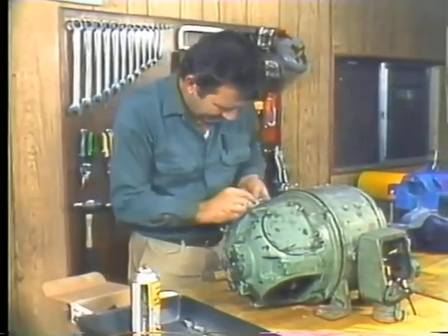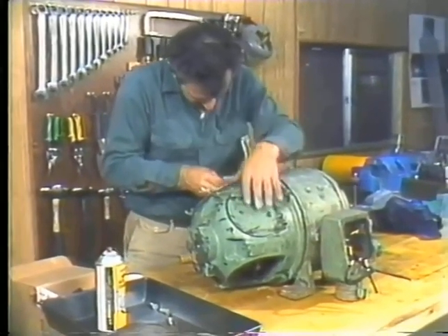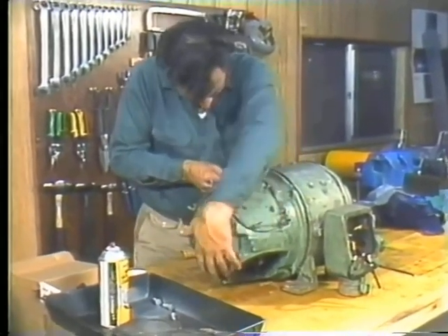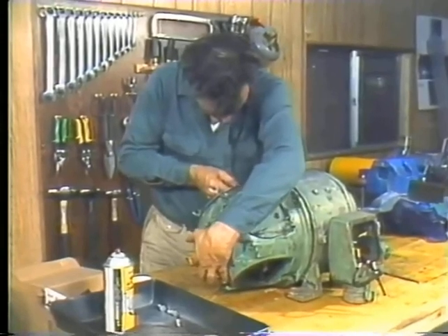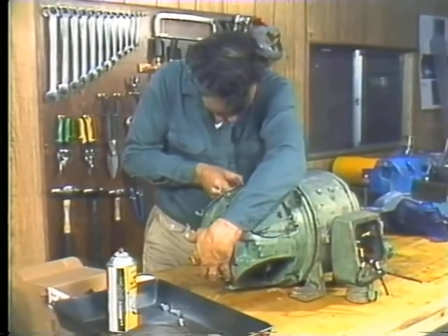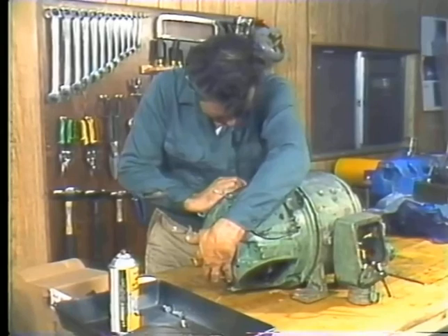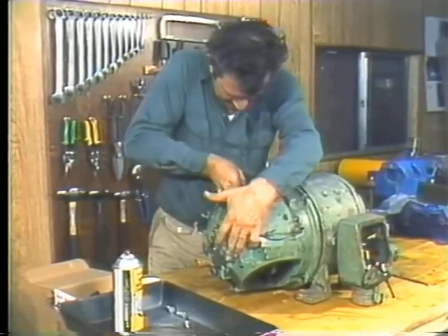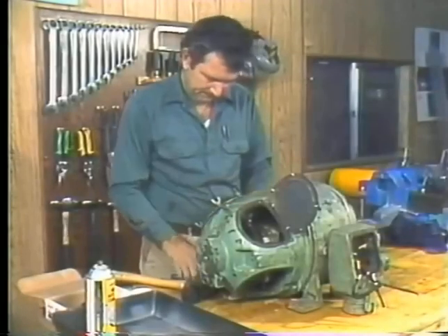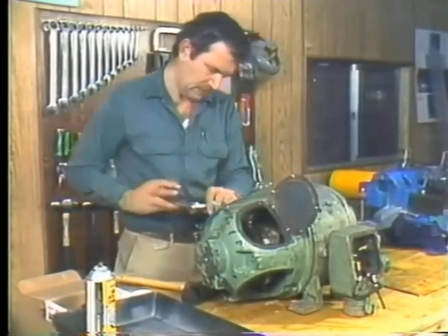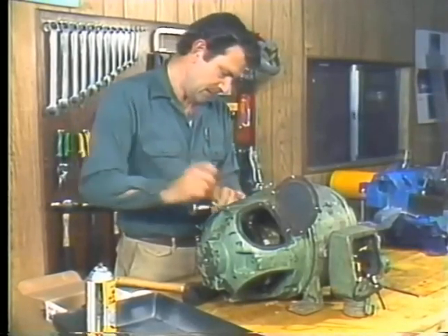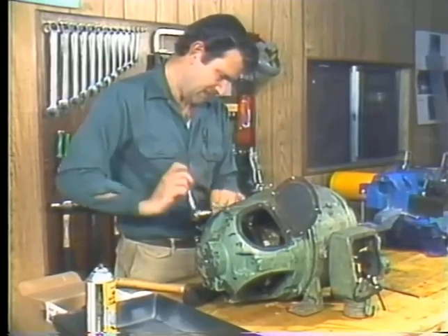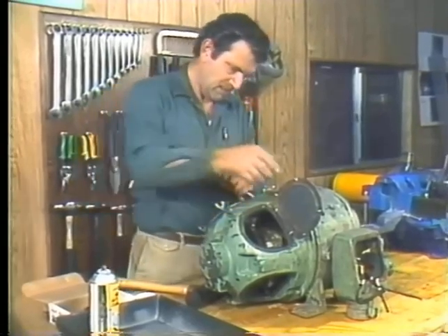Now, align the end bell and the frame marks and install the second set of end bell bolts after they've been lubricated. Use the bolts as a guide to align the end bell and the frame machine surface and tap the end bell onto the frame. Be sure it goes on straight. The crack between the end bell and the frame should be the same size all around the motor. Using the right size wrench, run the bolts so they're just snug. Don't put any pressure on them yet. We just want the bolts to hold the end bell right here.